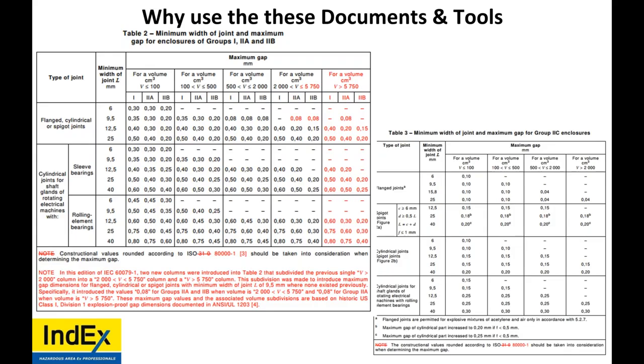How to know the original component arrangement and what is the limit of changing this arrangement? The difficult thing on an old installation, this is hard to find. On a new installation, the EPC really should be pushing the manufacturer, Stahl, Bartec, whoever it is, for a general arrangement drawing, which lists all the internal components.